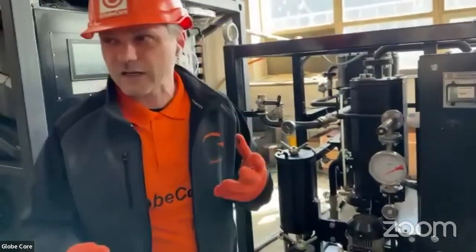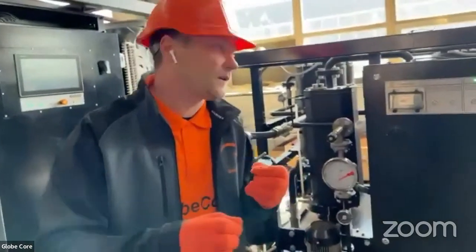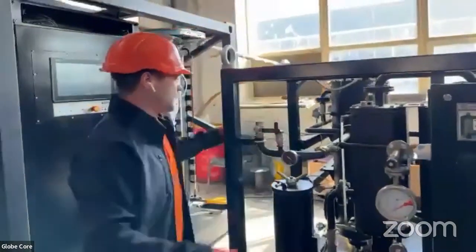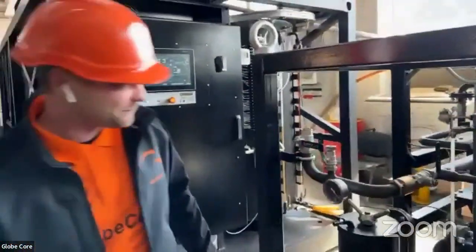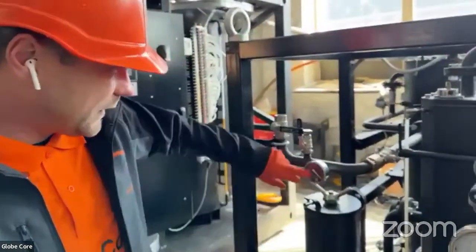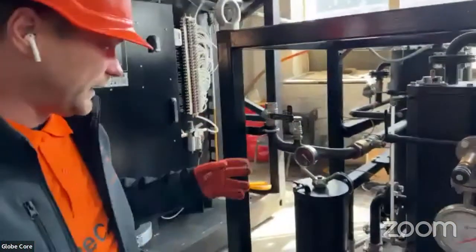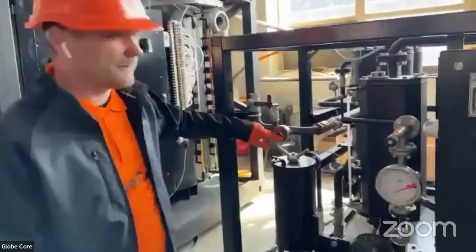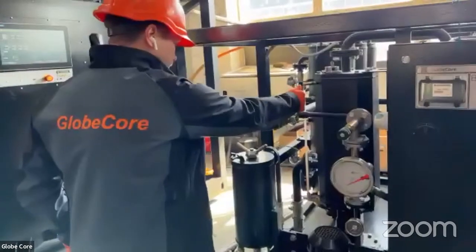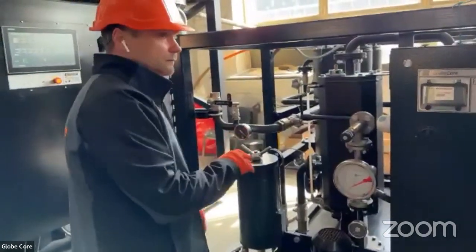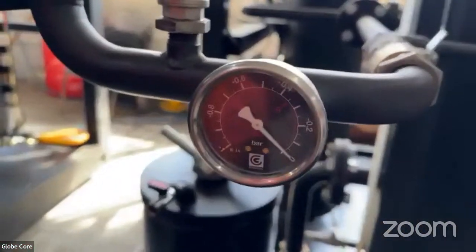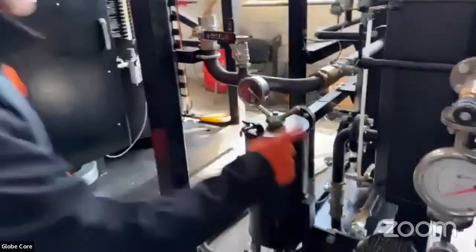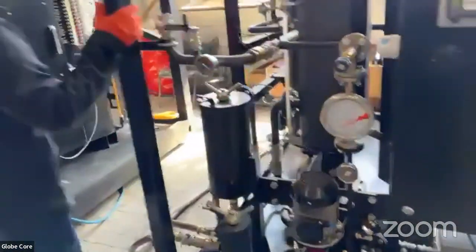The one thing I forgot to say is that the process takes place under a lack of oxygen, and this is why we have a comparatively small nozzle. You see, it's only 7 millimeters, and to control the amount of air, we use the vacuum meter in this line. We can control the amount of air going into the columns by adjusting the capacity of the vacuum pump with this valve.